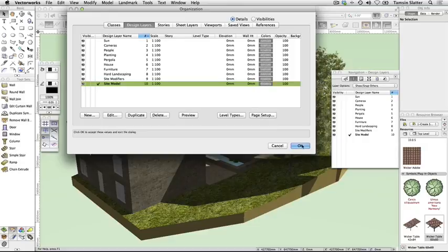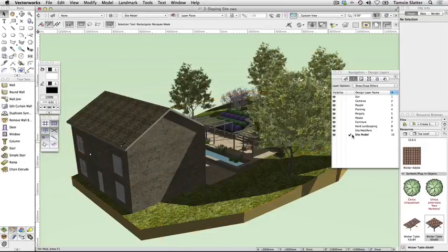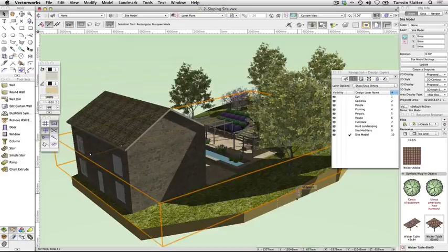Elements on these layers will sit on the surface of the site model. In this case, the site model surface has been created with stakes, but has been adjusted to suit the design. This is achieved with the use of site modifiers, which are beyond the scope of this guide. However, note that they enable you to impose your design on the site and determine the changes, including cut and fill volumes. Make Site Model the active layer.